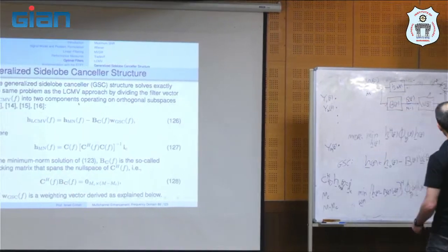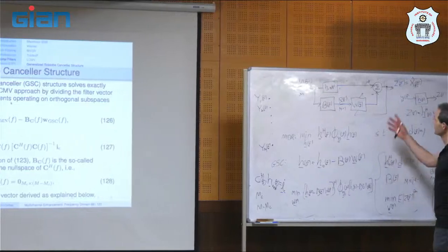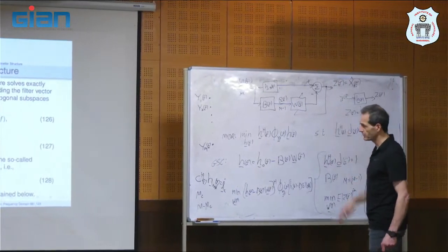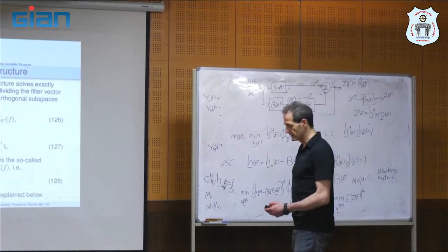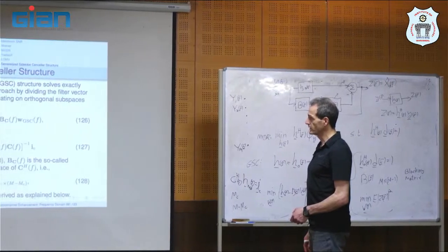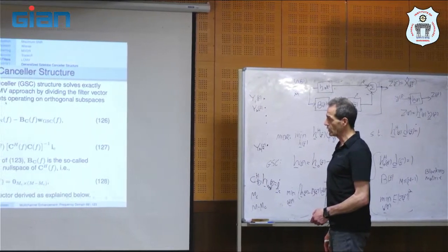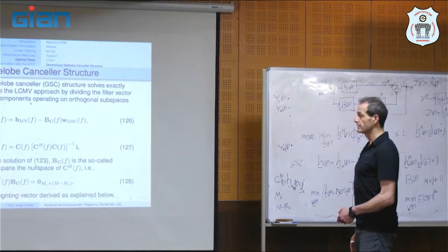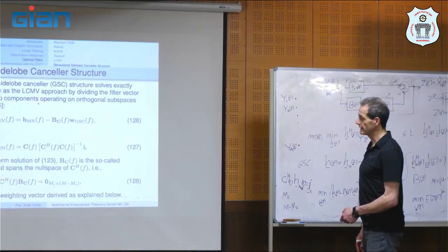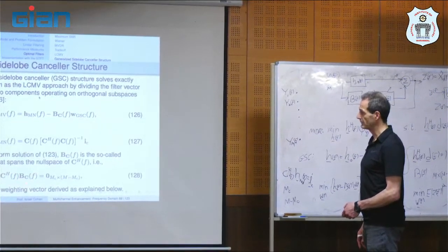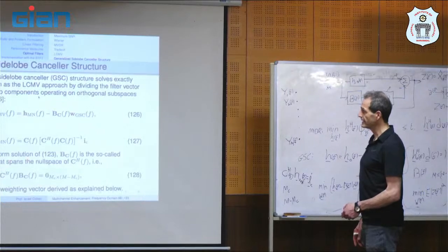You see, in this case, in the MVDR, it was what we wrote before, okay? So it's a blocking matrix. We showed an example how to block the desired signal. So actually, if we know the steering vectors of the constraints, so we know the matrix C, we can find a blocking matrix of size M by M minus MC, such that this will be satisfied.